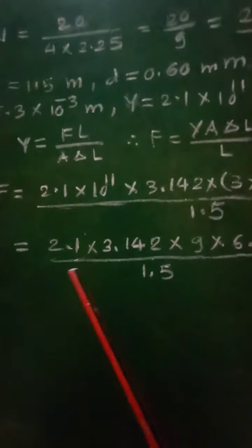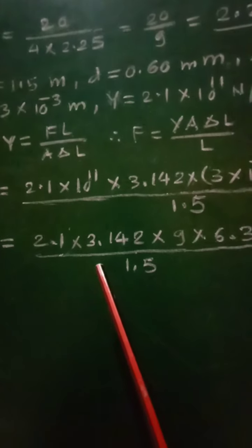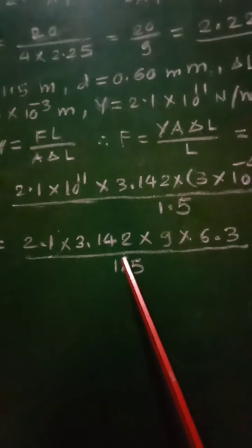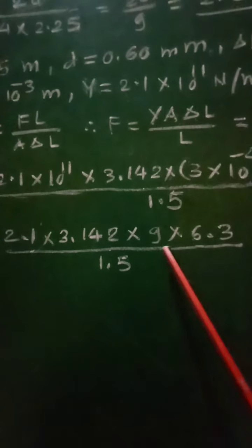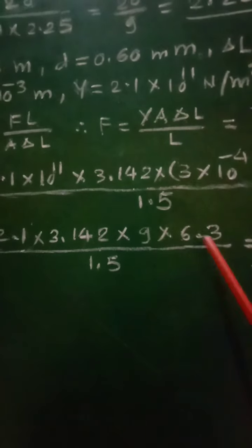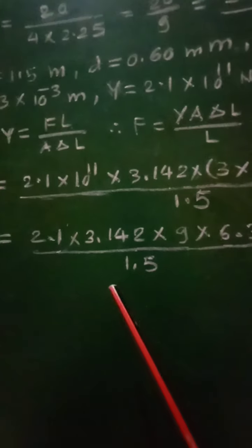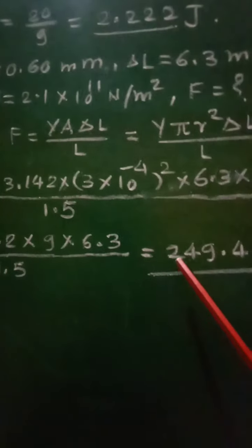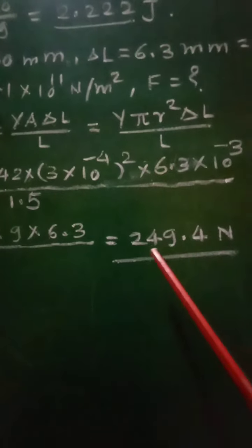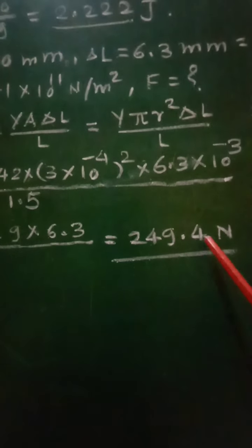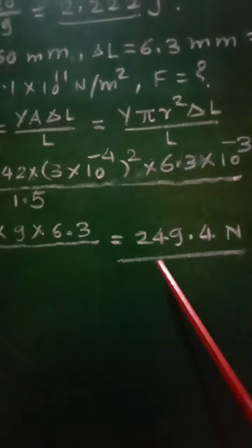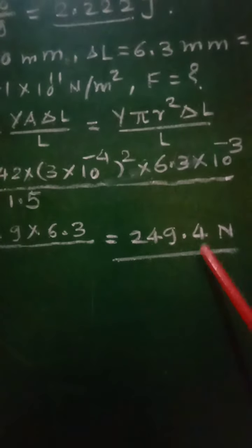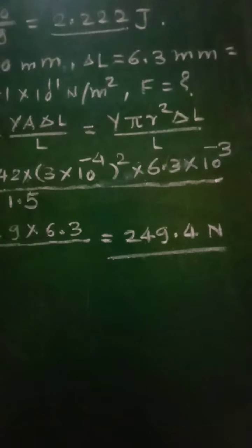By solving this, we will get 2.1 into 3.142 into 9 into 6.3 upon 1.5. By solving this, we will get 249.4 Newton, approximately it will be equal to 250 Newton. So this will be the force required.